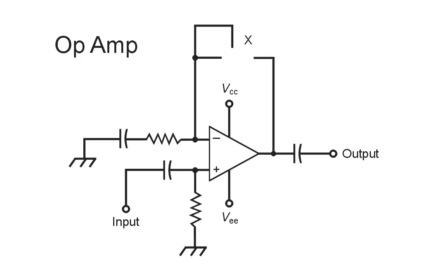But we do have this potentiometer, and this potentiometer, depending on what its value is, potentiometer X, will provide more or less negative feedback. So the lower the resistance of that potentiometer, the more negative feedback we'll get, and the less gain the amplifier will have. The higher the resistance of that potentiometer becomes, the greater the gain of this op-amp circuit.